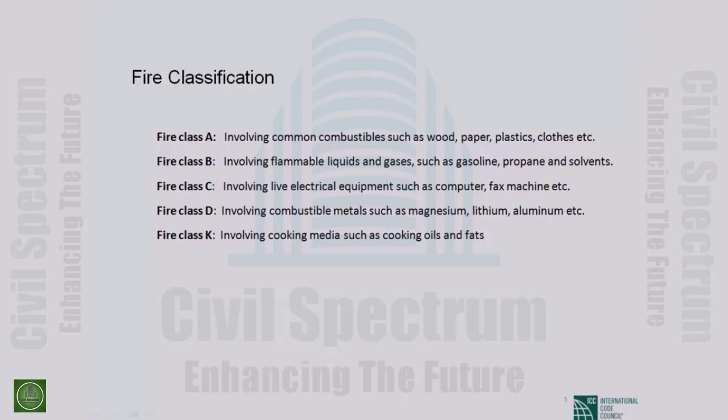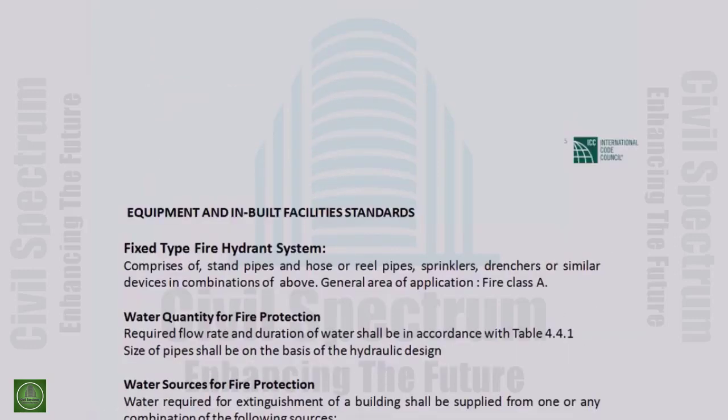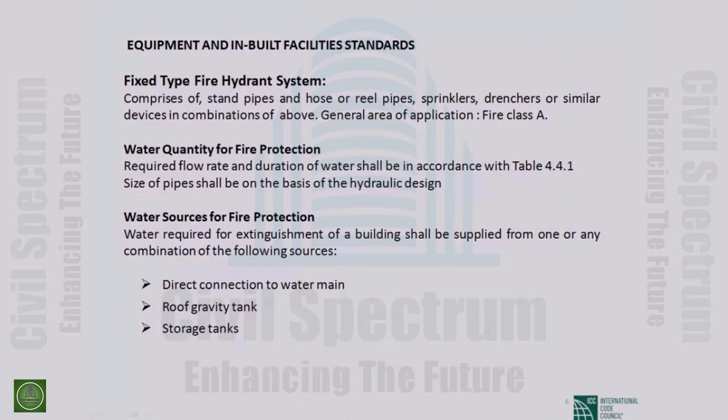In other thing, we have to consider the safety of the system. Actually, water is the best safe extinguishing system which can be easily used. Other type of system, gaseous or the other things, are not very safe system because they will create some toxic environment. So it is not very good for the inhabitants of the building. So you have to be very careful about using other than water as the extinguishing system.